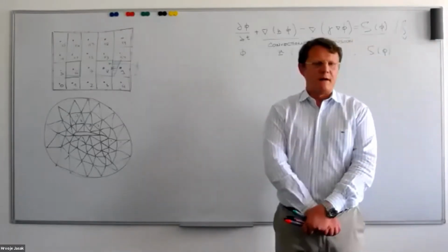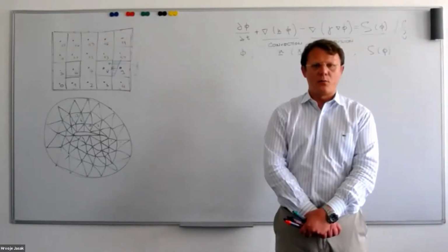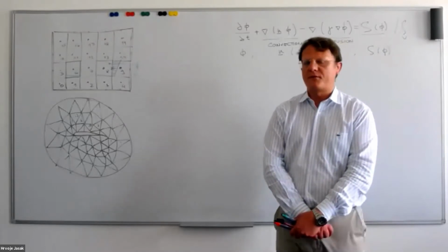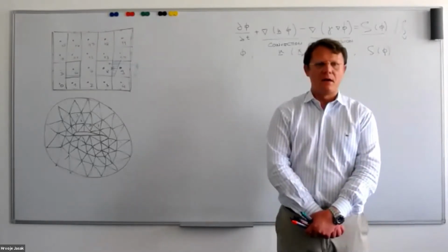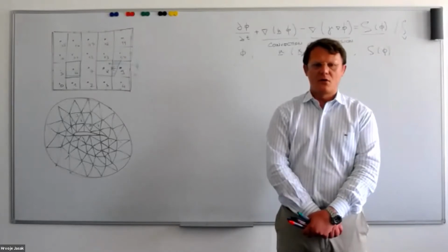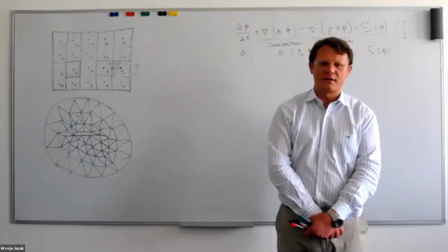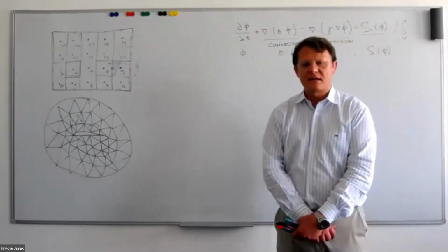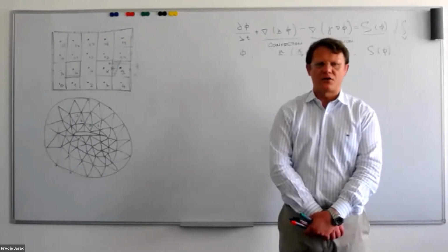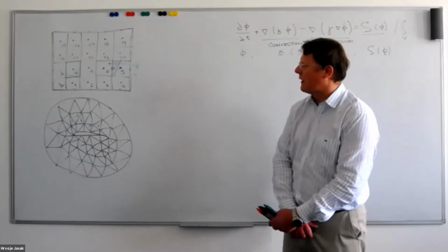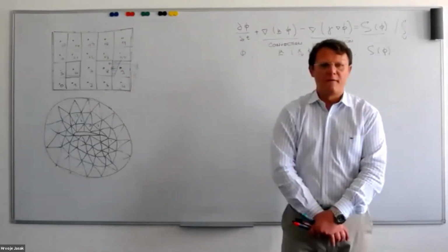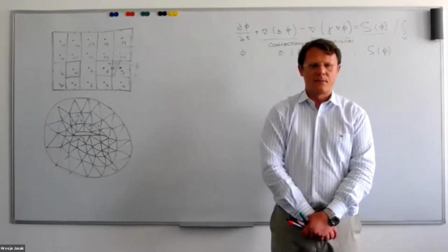So the story so far, we have split the computational domain into a number of cells and computational time into a number of time steps. From the mesh, we can know the cell centers, the face centers, cell volumes, face areas, and interpolation factors that allow us to calculate phi at the face, knowing the value of phi at the cell center.